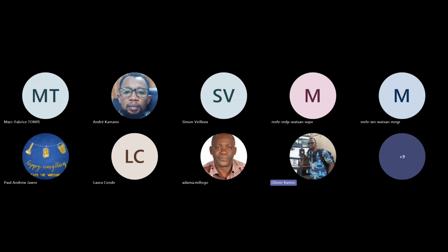If we take the rainy season safe yield or pumping rate and use it in the dry season, it can falter. So it is advised to run a pump test in the rainy season and again in the dry season, and then over the years we can assess how the borehole is functioning with what we are extracting.